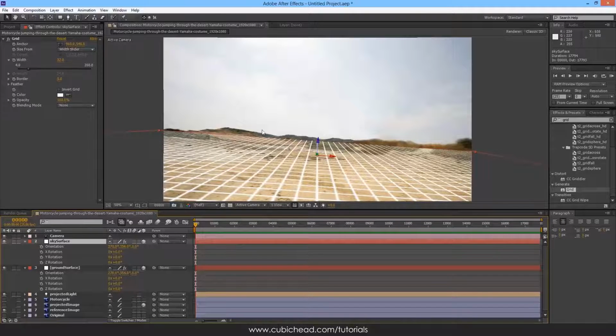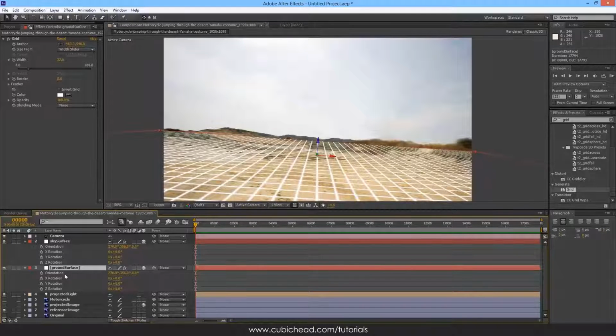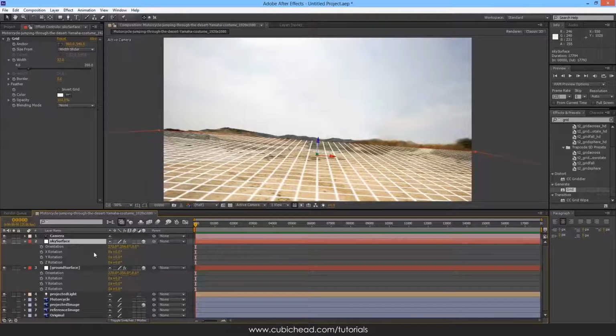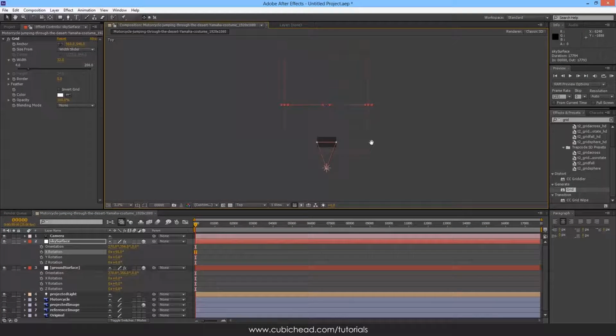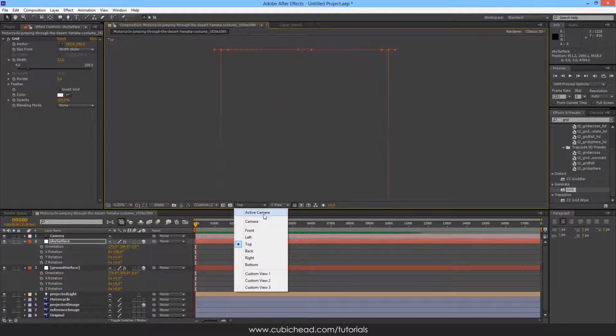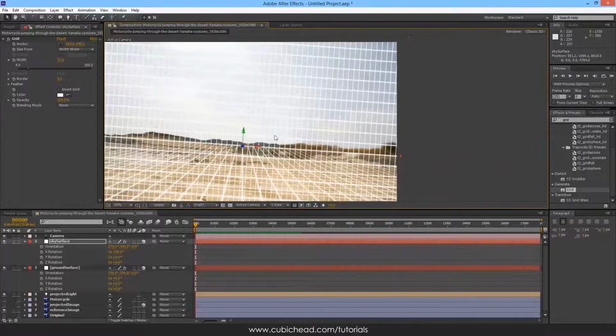Actually, you need to search for the vanishing point of this scene and then move the planes so you will be seeing the grids going to the vanishing points. And when you've got your first plane, the other ones are going to be settled easier because you've got the orientation of your scene. So remember, the first surface needs to be rotated through the orientation, and when it's settled at the right orientation, from that moment you could be changing the rotations. For example, in this case, I'll change the rotation of this sky surface into 90 degrees. Now you would be seeing that from here. Again, it's 90 degrees on our main surface, ground surface. I could reposition this from the top view. I'll get back here, the active camera, and here we go. We've got our scene.